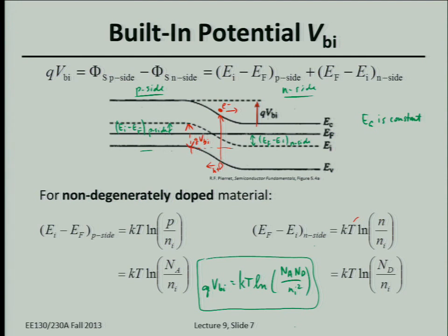One more thing: if you want to apply a voltage to a PN junction, you do have to change the charge stored, just like in a metal-semiconductor structure. So there's some capacitance, and the capacitance depends on the width of your depletion region. The narrower the width, the higher the capacitance. From a power consumption standpoint, it's not good to have high capacitance, because it has to charge and discharge to change the voltage in your integrated circuit. So for that reason, you don't want a very narrow depletion width, to save power, with lower small-signal capacitance. We'll go through that slowly in the coming weeks. Okay, but it's a good question.